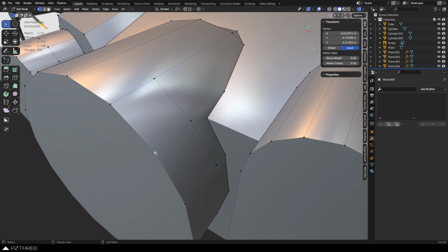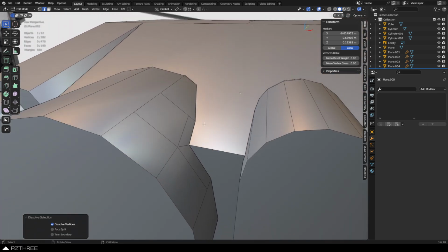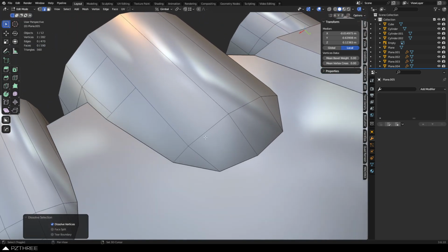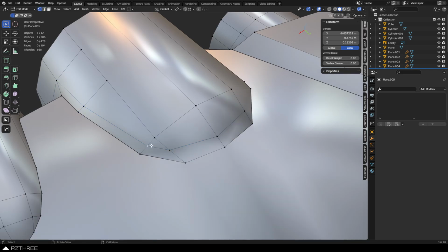So something like this right here, I really don't want this edge doing this. I kind of want this one to go up over here, but I want this to kind of go along the curvature here. And so eventually I'll have a holding edge like this, you see. So it's a little bit weird to cut some of this stuff up in this manner, but you certainly can do it. You just have to get used to using end poles to do redirects. If you watched my topology fundamentals video, you'll know that end poles are basically something like a quarter of an inset. Super useful and effective.